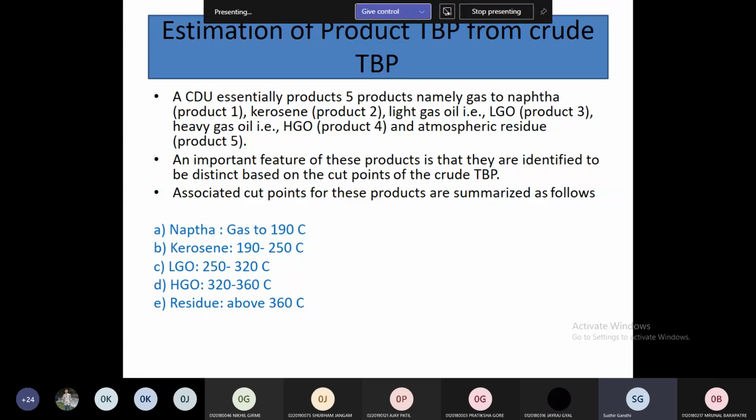The volume collected lets us understand how much will be the quantity of different fractions available in the crude oil itself. Then further, if more of the heavier fractions are available, if we are going to get more of the HGO and above residue, then the quantity and other things need to be considered for further processing, and the load needs to be calculated.